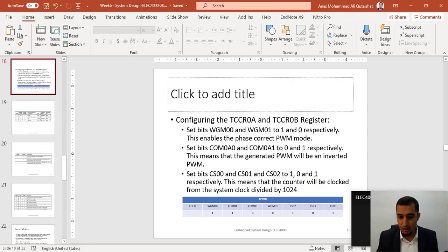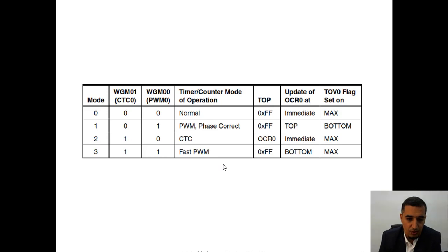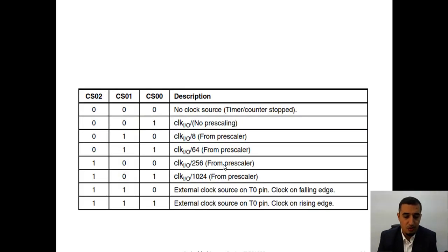What we started on last time was talking about how to generate a pulse width modulated signal using the microcontroller. Now, in terms of frequency, the only way for us to control the frequency was to use the prescalers. So if my microcontroller is running at 1 megahertz, what I can generate over here is 1 megahertz